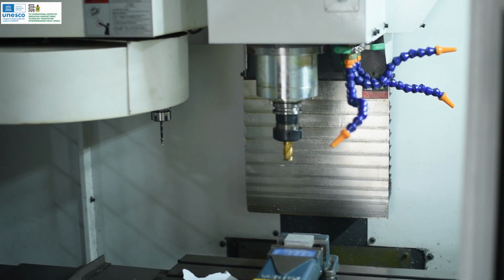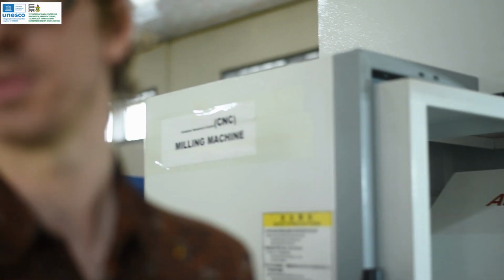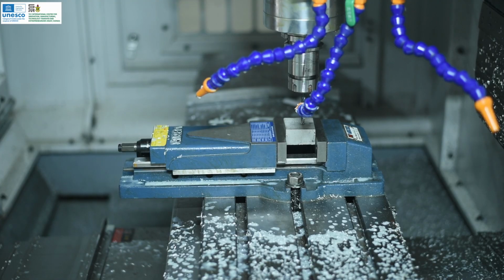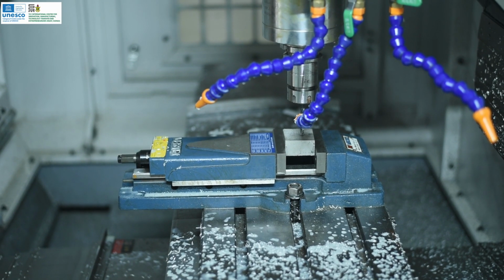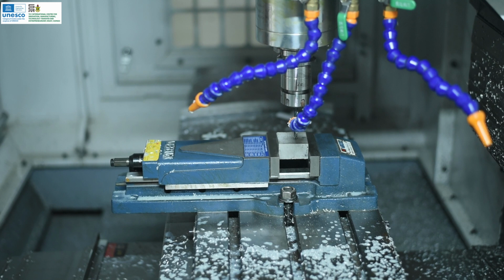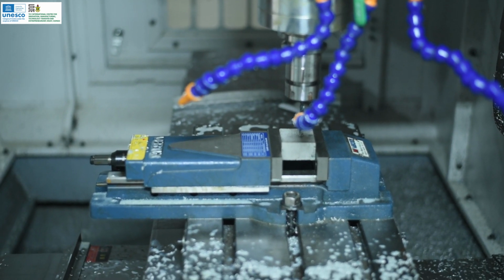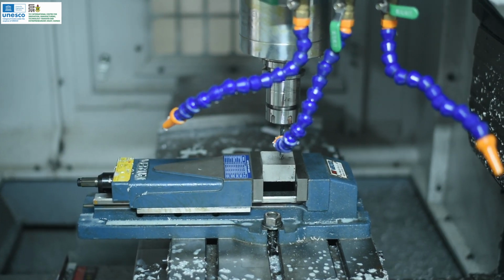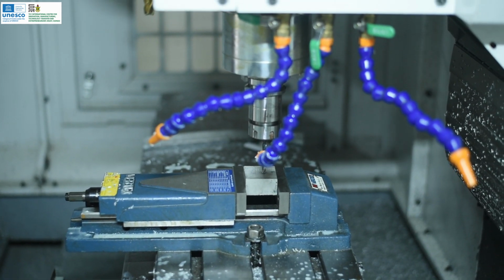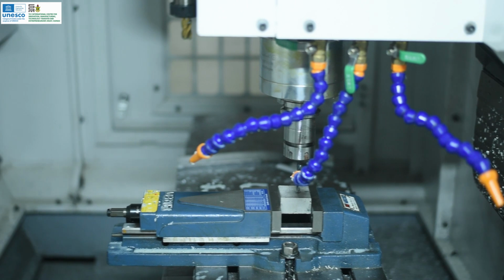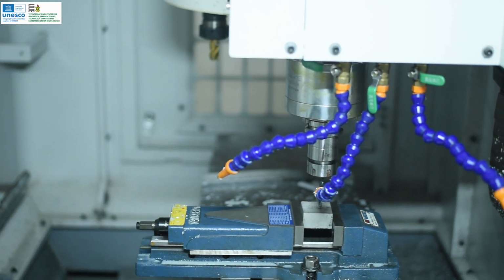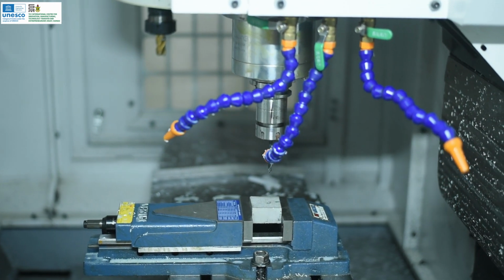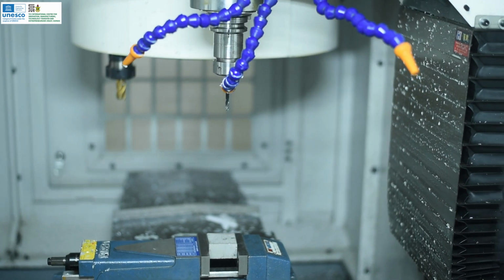And finally, with all our axes set, program set and edited correctly, our tool lengths are all set in the controller, we're now finally ready to cut. We're going to put it in run mode and in single block. Single block will allow us to run through only one line of code at a time with each press of the cycle start button. We'll close our doors and hit cycle start. It'll begin our program, and we'll keep going down in lines of code.